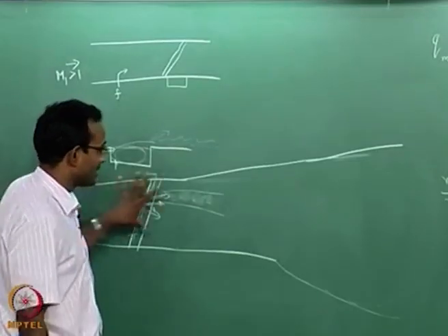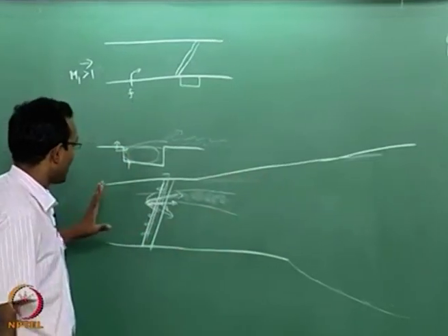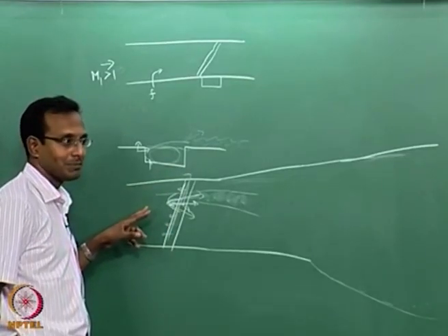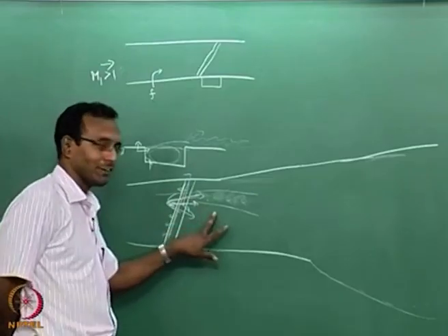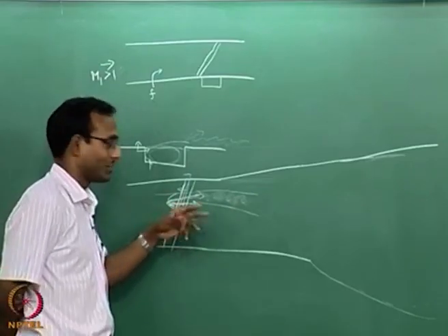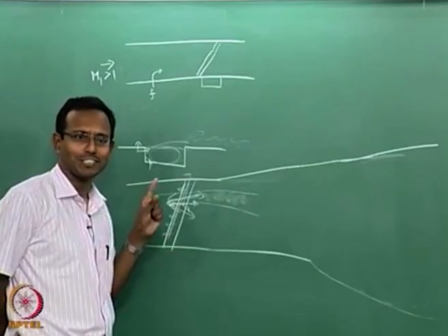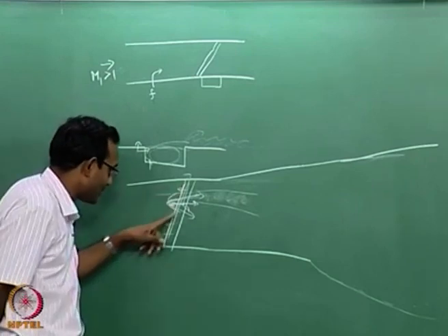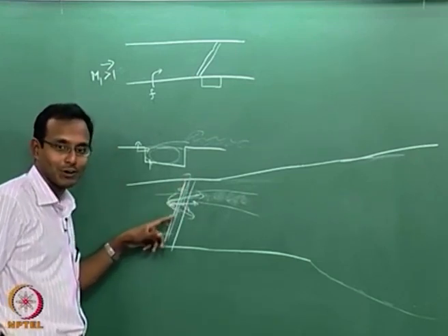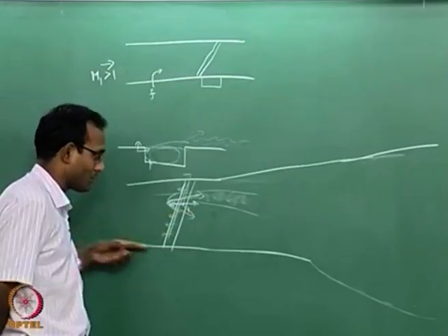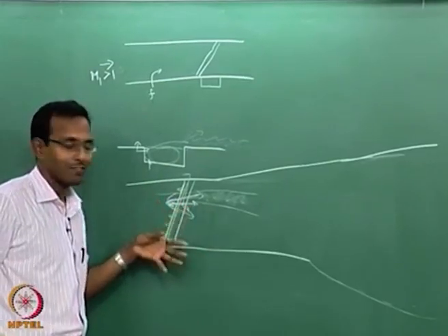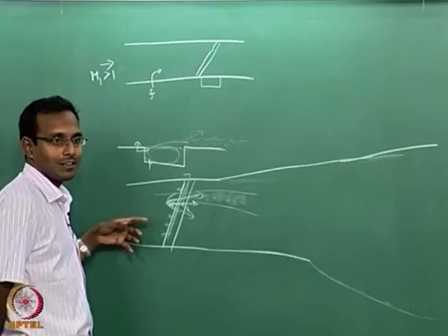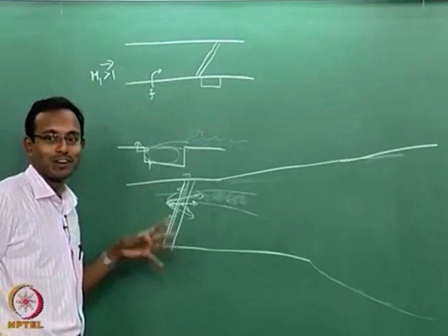Okay. So in this whole sequence, I am starting with a supersonic flow. I added a lot of things which decreased my P naught, and I added heat finally, which took me to M equal to 1 closer by all these means. I did not talk about friction in this whole thing. Now if I think about friction also, there is friction on this rod, metal to the gas contact here, or along the wall to the gas contact, friction is there. Everywhere there is friction, and that will also take it towards M equal to 1. That is why this whole problem becomes a little more tricky.